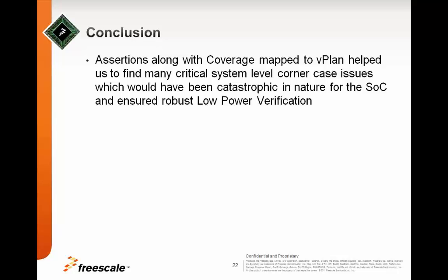Assertions also provide useful coverage information, in addition to a top-level system coverage on key signals, to measure the verification completeness. They can also be used across projects by creating template properties. Assertions along with coverage mapped to the vPlan helped us to find many critical system level corner case issues which could have been catastrophic in nature, and thus helped us to ensure robust low power verification.